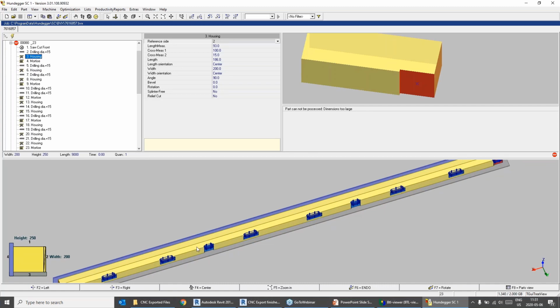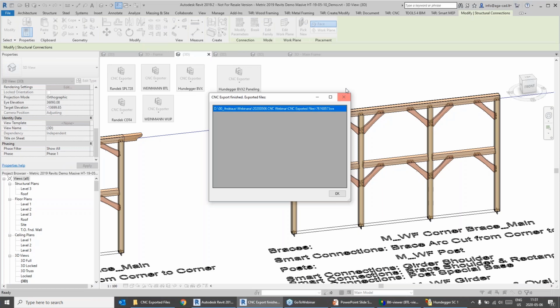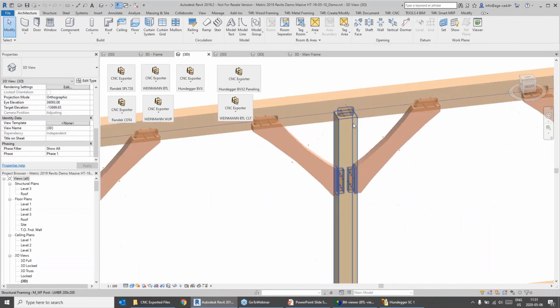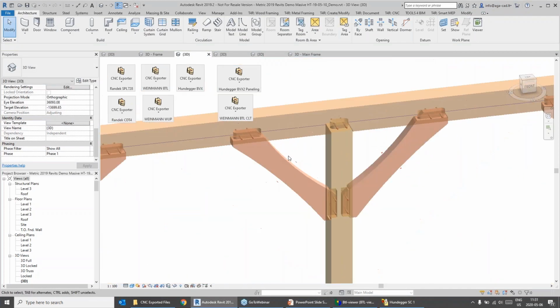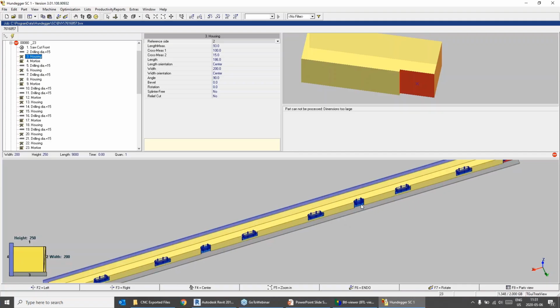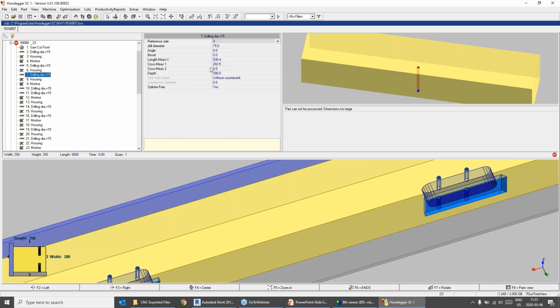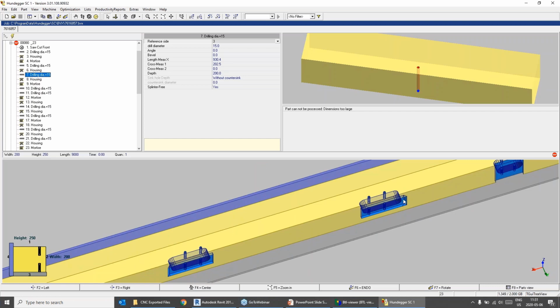So you see those connections for the studs, exactly the same ones that, sorry, I need to close that window again. So you see there were cuts made here, as well as those elements were connected through here. And then I'm having the column connection and two connections for those braces. And all those things are detailed with all the commands, what the machine should do, with what kind of values, how deep should it drill, how deep should it mill,